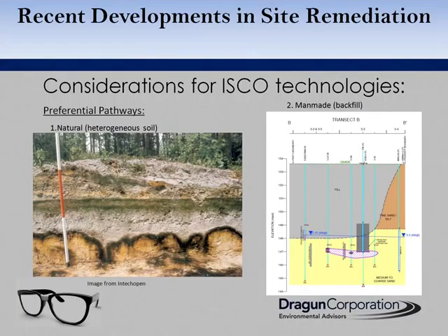However, the final 10% was overlain by a significant area of backfill that you can see as gray in this slide, and a large diameter pumping well surrounded by high conductivity gravel, which is the darker gray. And this rendered ISCO relatively useless at this site, and we had to reevaluate our options. Heterogeneities in soil also lead to common post-ISCO remediation effects, commonly referred to as contaminant rebound or matrix diffusion. On the next slide, my co-presenter and fellow environmental engineer, Matt Schroeder, will show you a brief video on the effect of matrix diffusion.